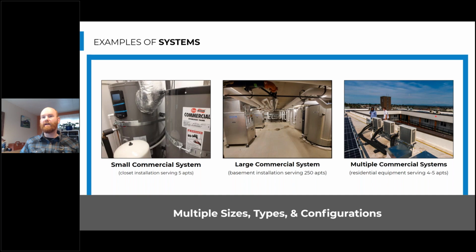Because these are small residentially sized products, we couldn't serve 20 units with one of these heat pumps, but we can serve 3 to 4. This project we broke up into, I think, 12 plumbing zones, and we're serving these vertically. It does mean more maintenance points, but it does give you some redundancy in your system as well, to an extent.